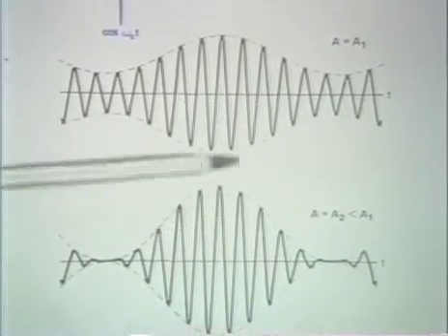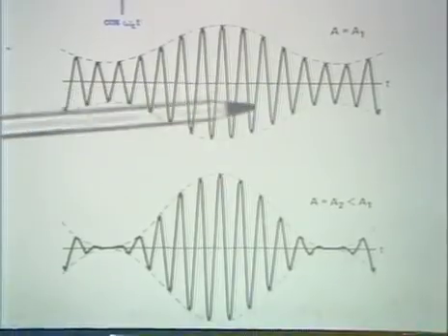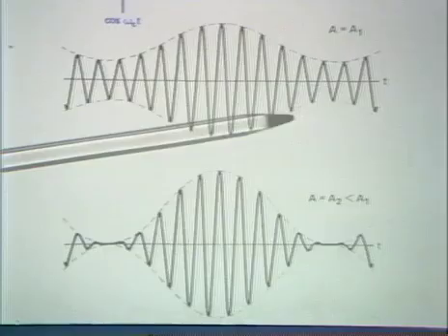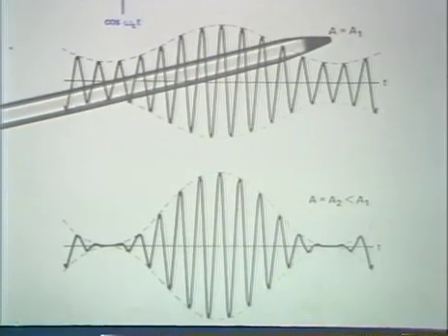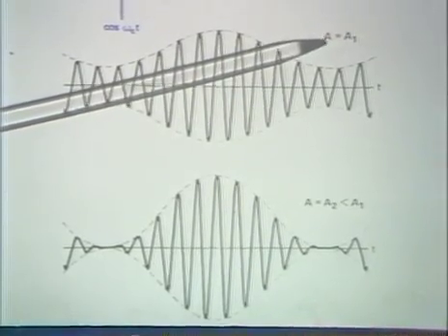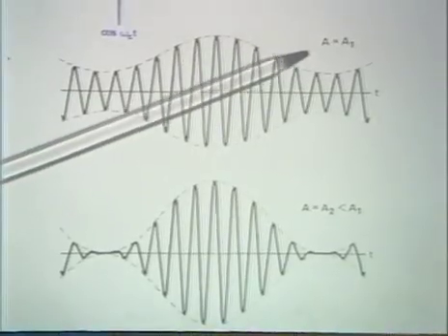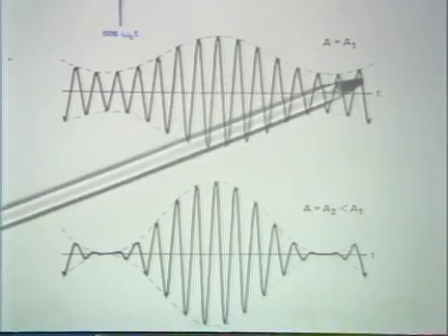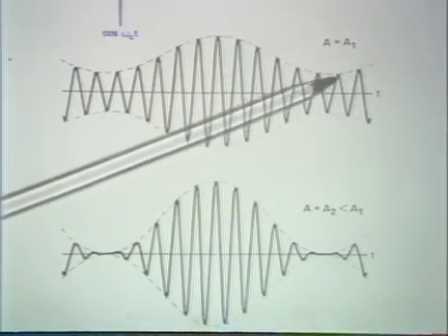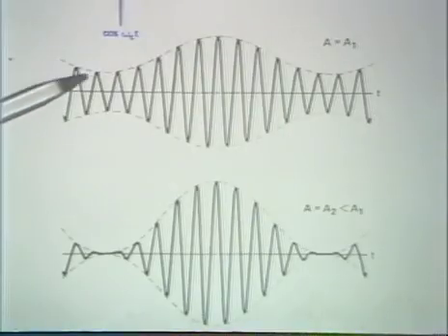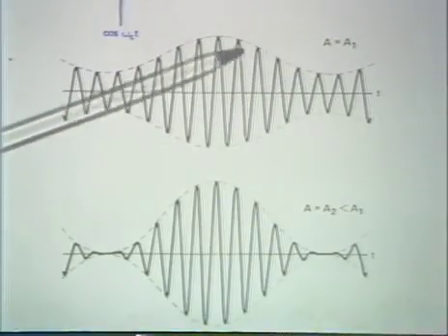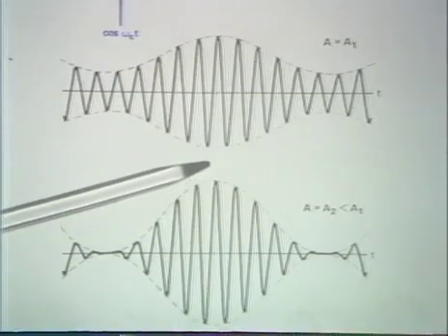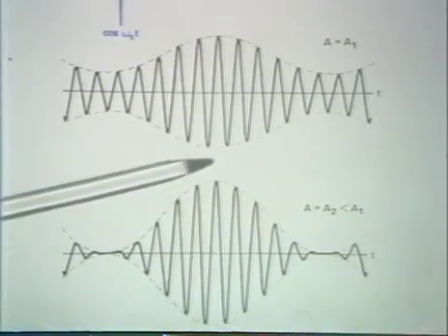There are both positive and negative issues associated with whether A is too large or too small. For example, if A is large in relation to the amplitude of the signal, then this envelope tends to be very flat, and it tends to be easy to track it with that simple diode RC circuit, as compared with the case down here.